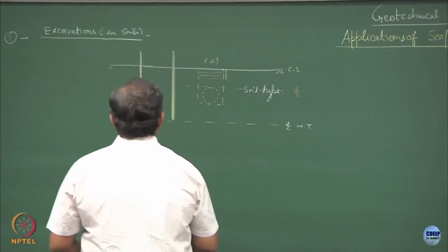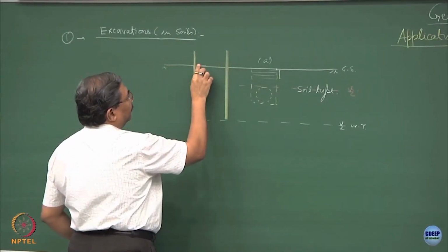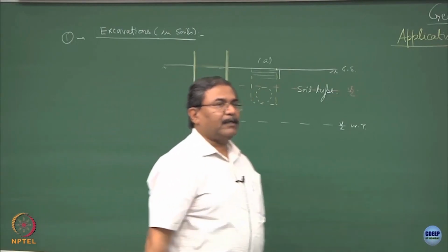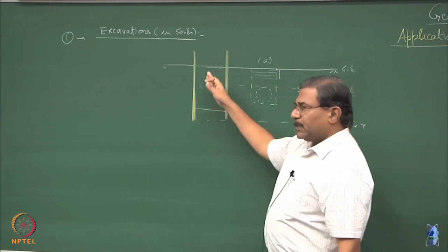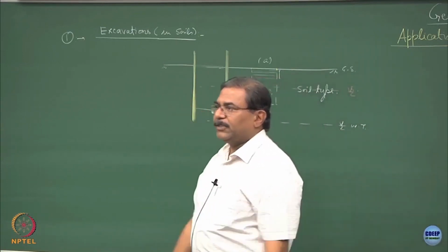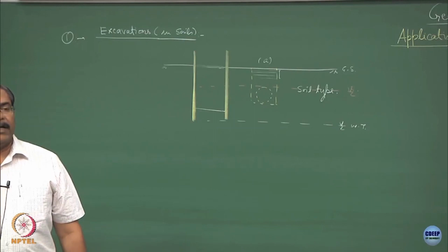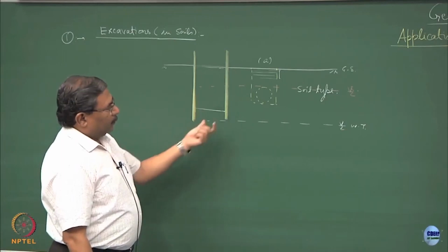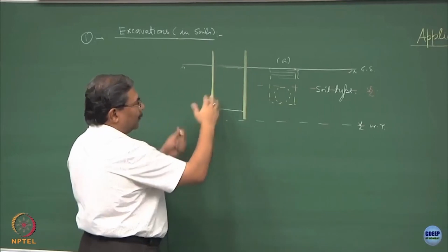Now, I hope you can understand, once I have retained the soil mass, I can start excavating layer by layer and I can achieve a certain required depth. Is this part clear? So, this is the excavation by employing sheet piles. If you are interested in knowing how the insertion is done, you are free to watch videos. There are many countries including India who have become pioneers in inserting the sheet piles and utilizing them. So, ultimately I have created the space. I hope you can realize this, alright, and I can do whatever I want to do.